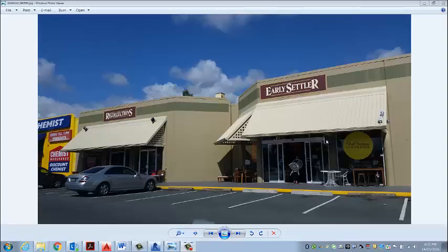Now that I've completed this part of the shop front, you can see I can now use the same methodology to create this area, which is just one fixed curtain wall panel with the mullions around. And again here, remember I was going to go and find in the Revit library and online these sliding doors, but here you can see they're the same doors that we've just applied. So looking at each shop individually, looking at each one of those photographs, we'll be able to get an idea of the size and the information required.